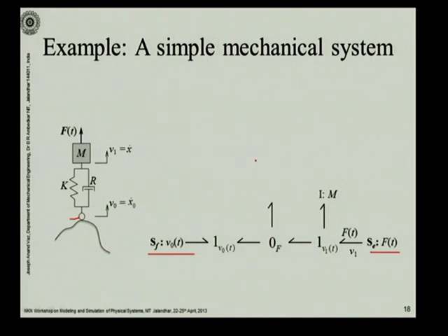So you are determining what is the relative motion across this. And you know that the same relative motion is common to both the C element as well as the R element, the C element representing this spring and the R element representing this damper, and so we are going to use a one junction because it is common. So we have a C element and an R element connected to this. I hope it is clear to you.